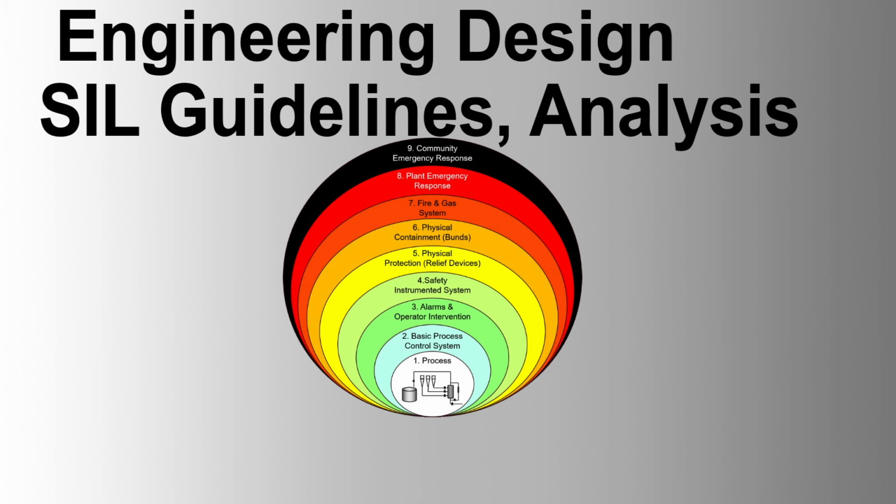Calculation of probability of failure on demand, PFD. Understanding failure rates. Failure rate. The failure rate of each component involved in the SIS must be determined. This includes both dangerous and safe failures. Dangerous undetected failures, DU: failures that do not get detected by diagnostic tests and can cause the SIS to fail on demand. Safe detected failures, SD: failures that are safely detected and do not lead to a system failure on demand.